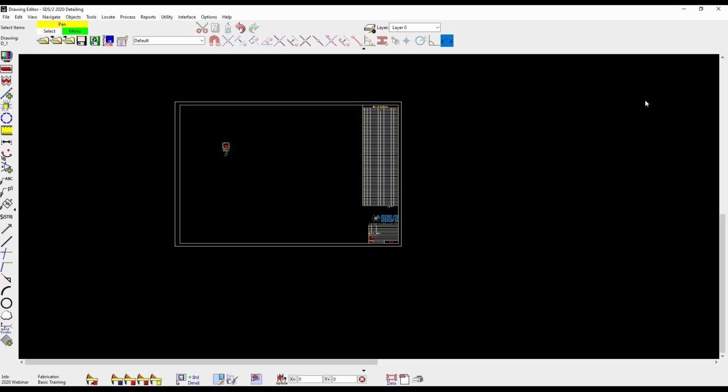Can you do a single bevel prep in the model for CJP welds? It's only going to prep what the system does automatically with that. There are options, though, when I add a weld manually that I can get it to do that weld prep.